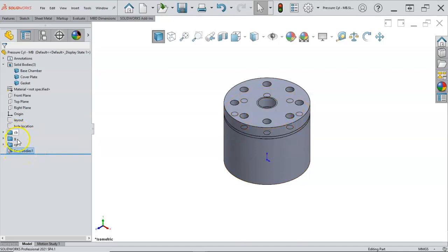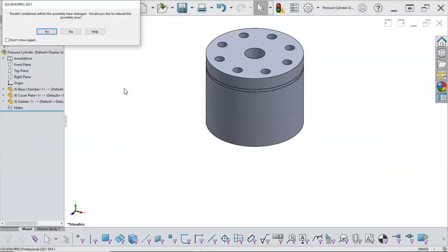Anything that I do to the model before, and this may be where you don't want to suppress anymore. If you suppress one of these objects, it's going to rename, and if you have a lot of solid bodies in this strategy, then that can be difficult. So the rollback is a much better strategy, and it doesn't lose its mind. Anything that we put in after the Save Bodies is not going to participate when we go over to the assembly.